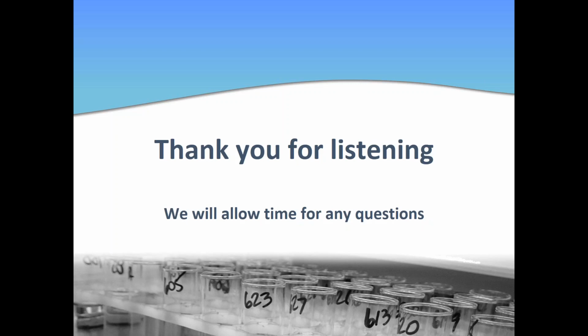For everything I just described there to you, the spectrometric, water content, wear particle classification, or ferrous wear concentration, sorry, and the ferrography, generally speaking, if you can fill a 5 ml syringe, 5 grams of sample, that is enough for us to be able to do that testing. If you can give us more, it helps us if there's any need for a rerun, and helps make sure we can get as representative of a sample as possible. But we're not requiring large volumes of grease here.